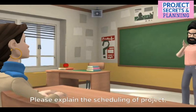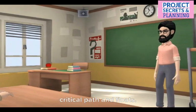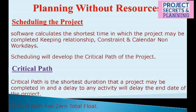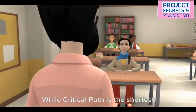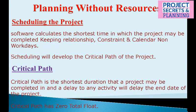Now Ashu, please explain the scheduling of project, critical path and floats. Yes, sir. After making relationships, Primavera calculates the shortest time in which the project may be completed, keeping relationships, constraints and calendar non-workdays in view. Scheduling will develop the critical path of the project. The critical path is the shortest duration in which a project may be completed, and a delay to any activity will delay the end date of the project.